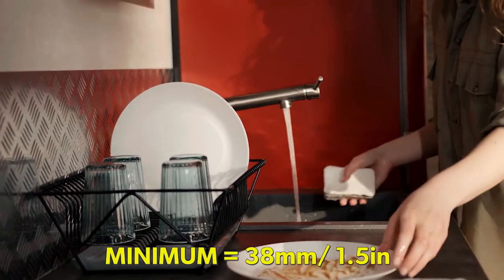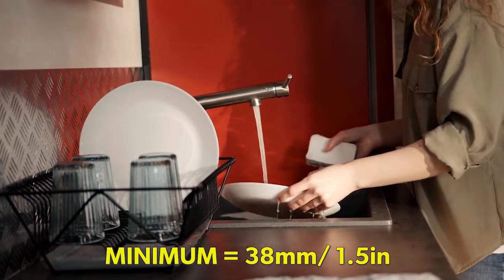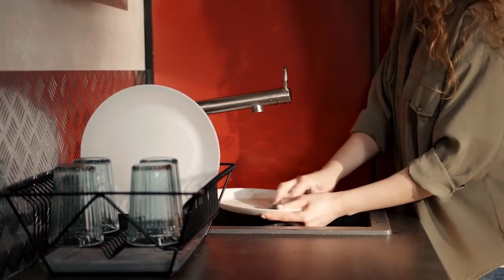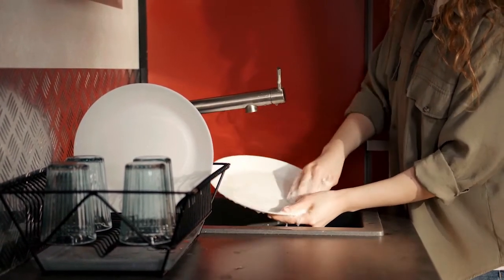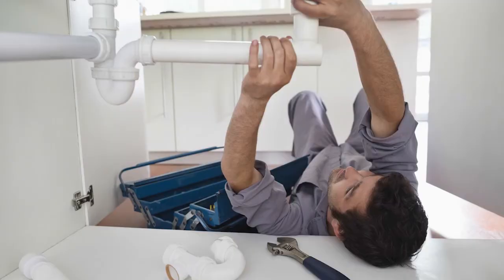The minimum size of waste pipe for sink is 38mm or 1 1/2 inches. But because of the material suspended in it, the practice is to use 50mm or 2-inch pipe. The National Plumbing Code provides that the waste pipe must be short, direct, free from offsets, and provided with ample cleanouts accessible for repair.